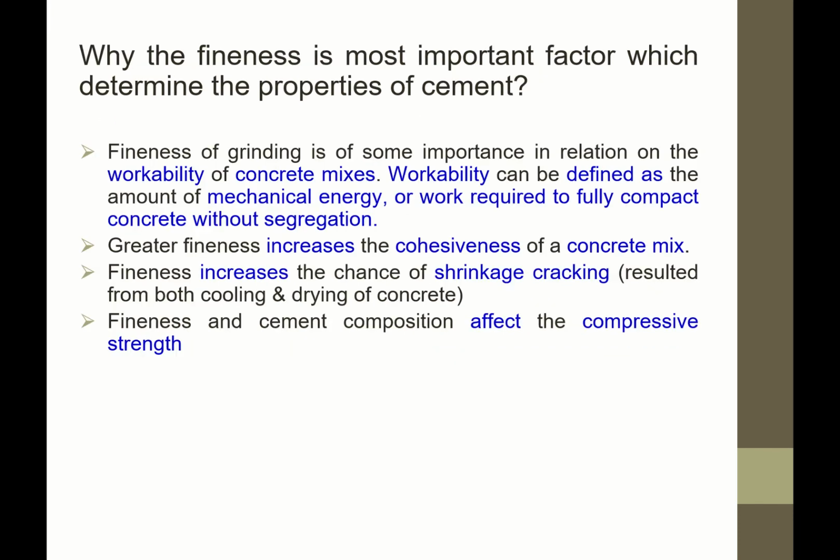Why is fineness the most important factor which determines the properties of cement? The first thing is that fineness of grinding is important in relation to the workability of concrete mixes. Workability can be defined as the amount of mechanical energy or work required to fully compact concrete without segregation. At the end of the day, we want the best quality of concrete. So fineness is always related to the workability of concrete mixes.